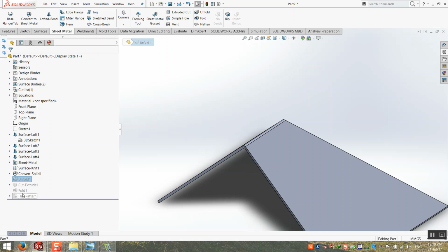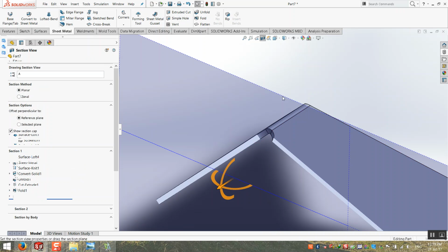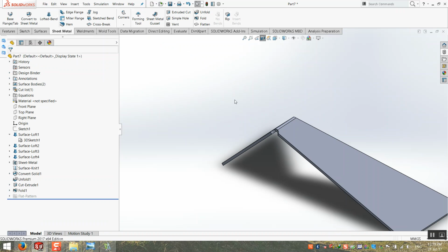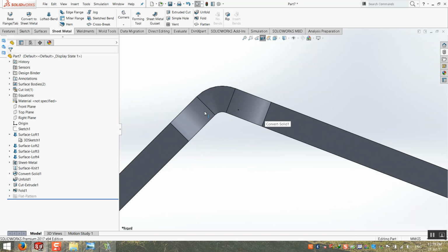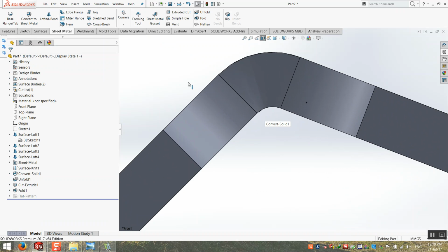Why? Because here, if you get a cross section, the thickness of the sheet metal is perpendicular on the faces, because this operation was already made in laser cutting. But if you just do drilling, the faces will be like that. Yes.